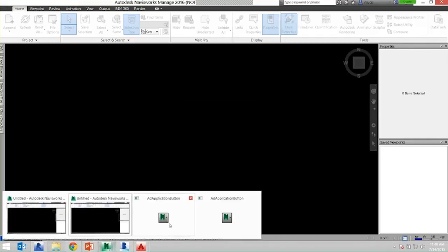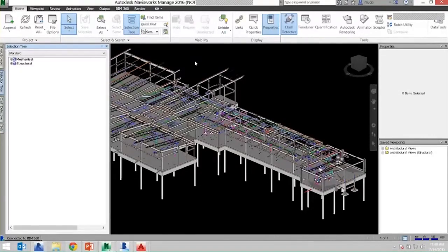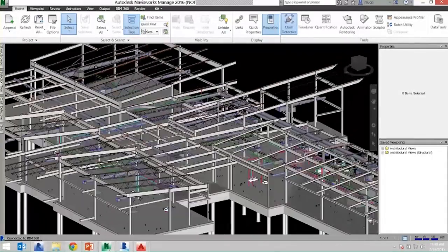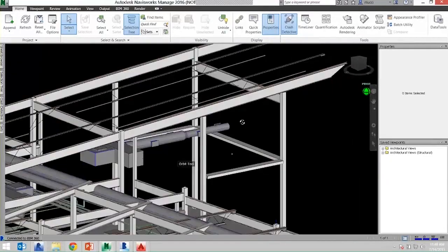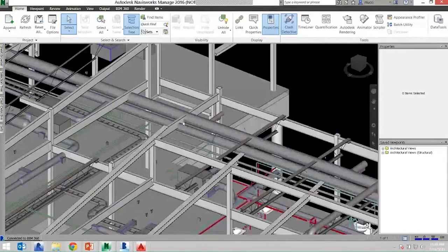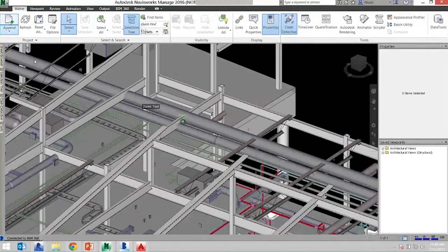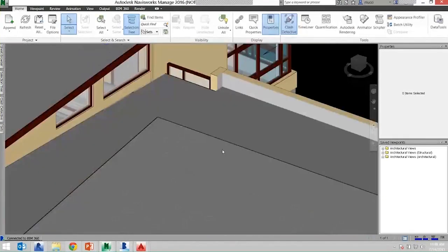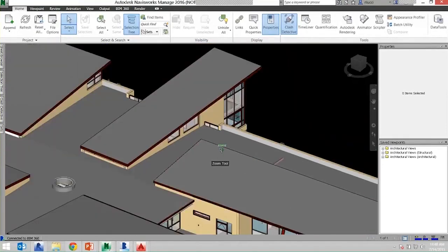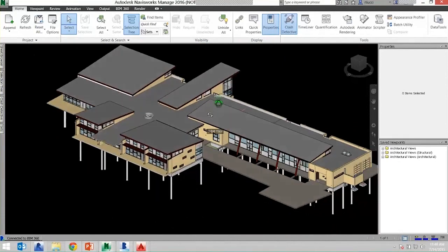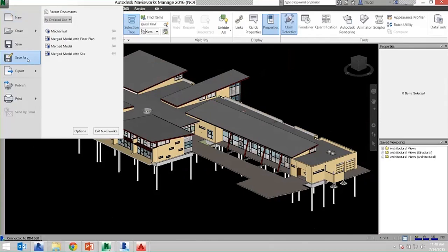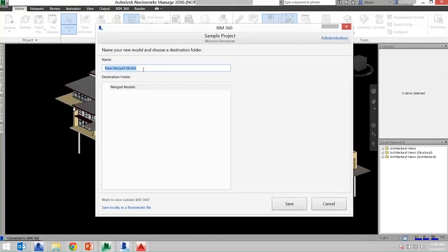So I'm really stressing out my system here. That's okay. So here's Navisworks. Currently, it's got mechanical and structural, right? I could do my clash detection to find where mechanical hits structural, everywhere. And then I'll say, well, now I need to append the architectural component, and I'll just go ahead and append another file. What we're basically doing is using all of the parties that may not have Navisworks. They're contributing their files, and then I'll be able to do a Save As, make a new merged model, and load it out to the cloud for everybody to review.